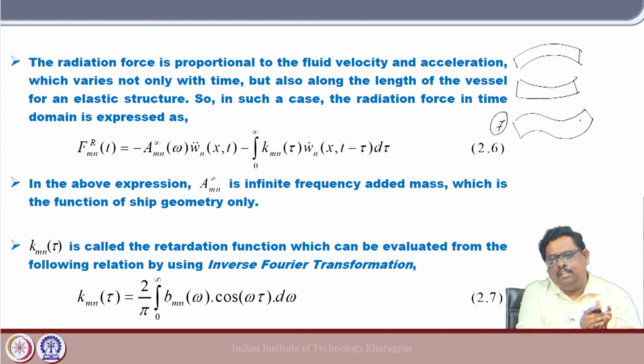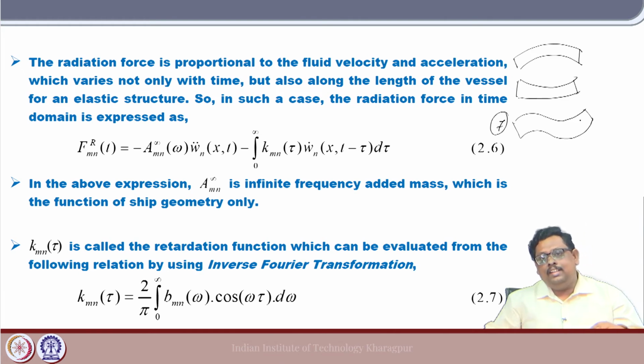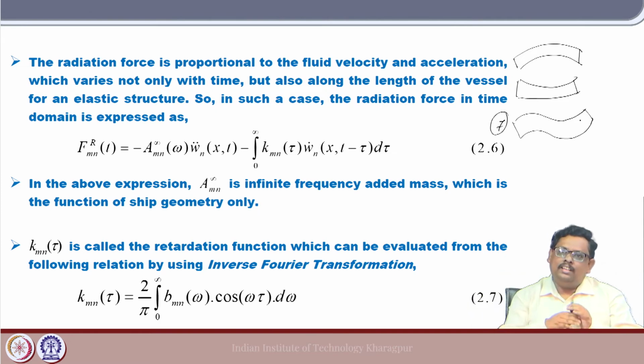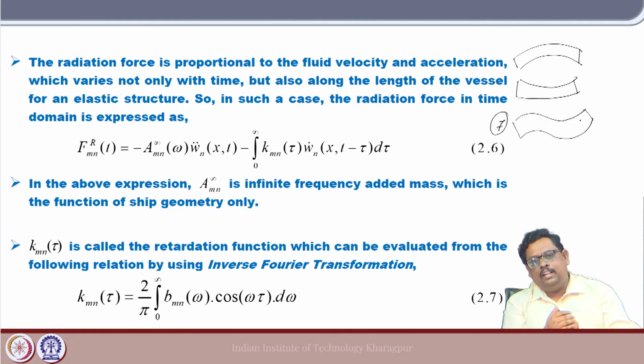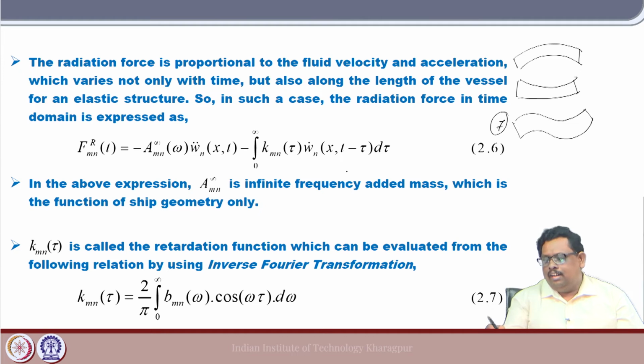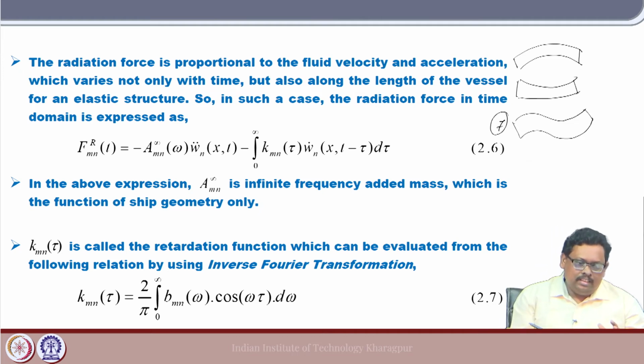In case of flexibility, it is far more critical to realize that when a body is oscillating in this way, what is the contribution in the force in that other mode when it oscillates in this mode? So, to make it a little bit simpler, what we normally assume in case of hydroelasticity is that we do not consider the cross coupling.